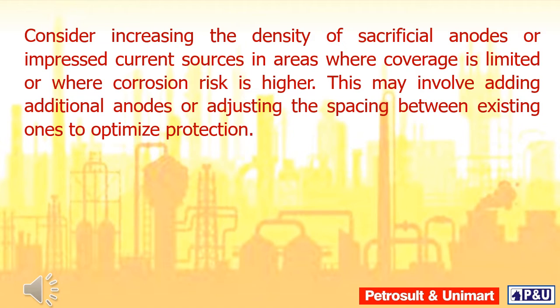Consider increasing the density of sacrificial anodes or impressed current sources in areas where coverage is limited or where corrosion risk is higher. This may involve adding additional anodes or adjusting the spacing between existing ones to optimize protection.